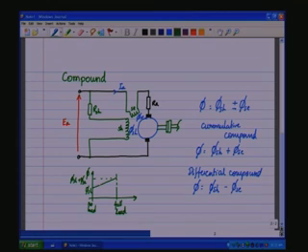So, as the flux increases, you saw that the back EMF is connected across the armature winding, and if you say the back EMF is constant for a given speed, then as the flux increases, the speed will reduce. Which means that as the load is changed from no load to full load, flux is increasing and the speed will reduce. And in the case of differentially compound, as the load is increased from no load to full load,